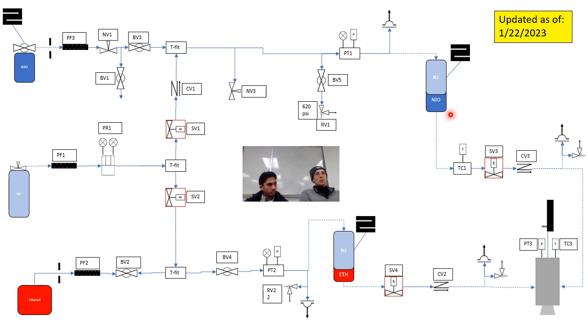And at that point, we can get our minimum pressure from 820, which was at room temperature what liquid nitrous oxide stays liquid at, down to 620, 600, and really 450 psi, which is the pressure that's needed to keep nitrous oxide liquid at 0 degrees Celsius.